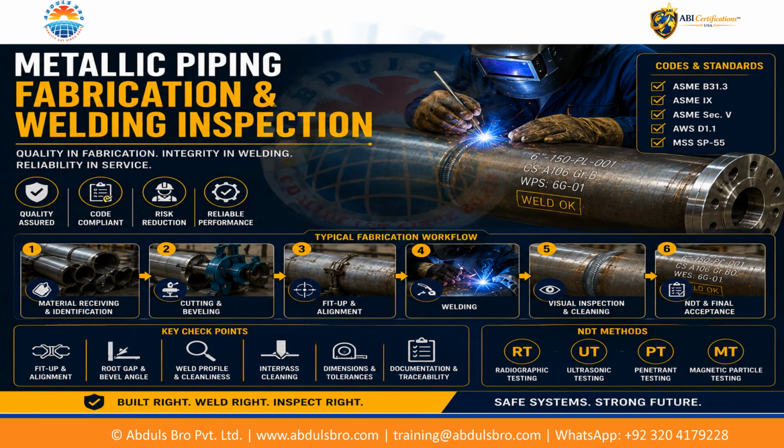Metallic piping fabrication inspection starts with joint preparation, fit-up, alignment, and dimensional verification before welding. QA/QC personnel confirm that welding is performed using approved procedures and qualified personnel, while maintaining weld identification and traceability. Completed welds are subjected to the required visual inspection and NDE in accordance with the applicable requirements. Branch connections, attachments, and flange alignment are also verified together with post-weld heat treatment where specified before the fabricated spool